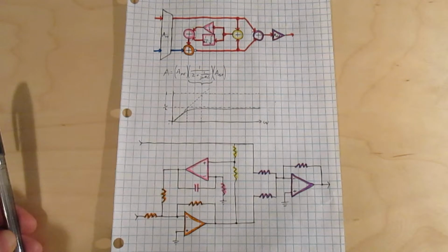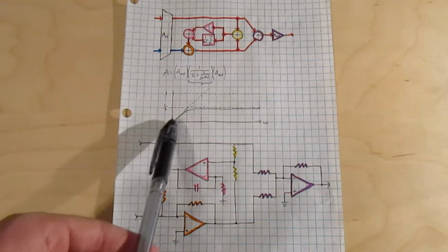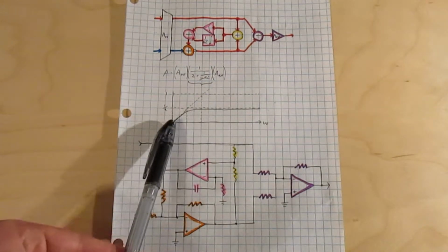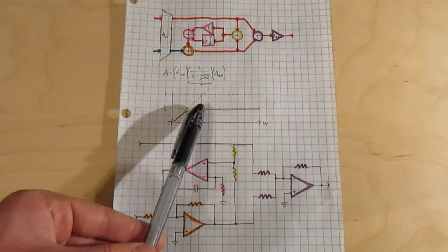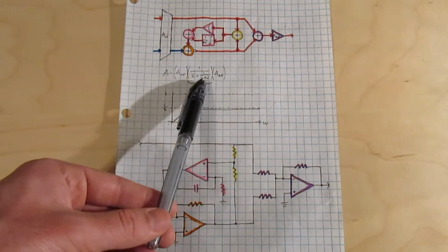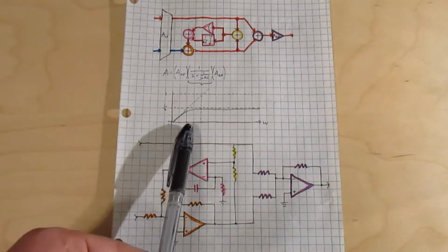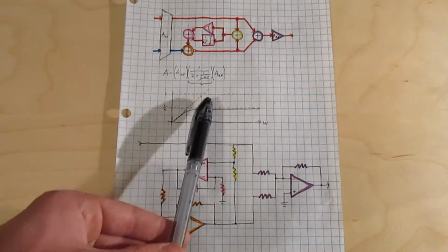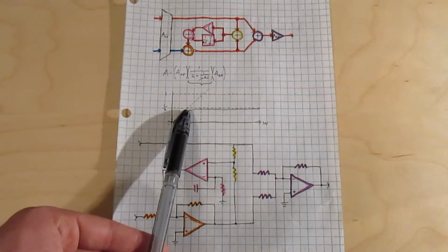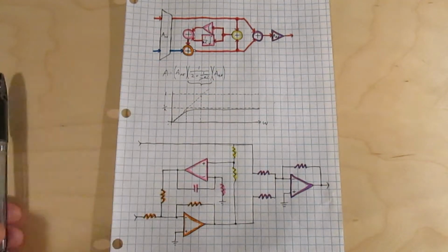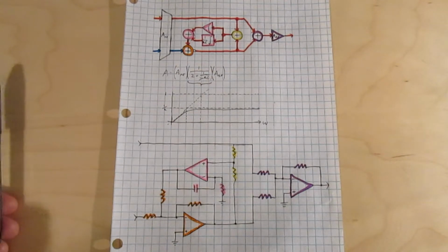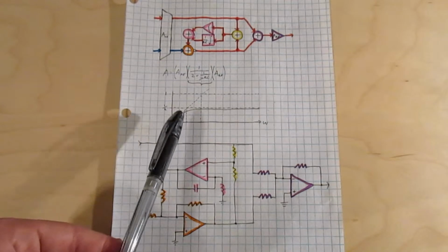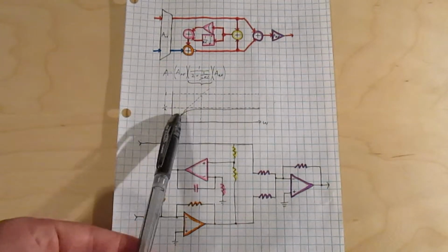But the gain reduction also does something else interesting for us in terms of the frequency response. If you look at the plot, there's some corner frequency where the gain starts to level off, and that's the point where this 1 over j omega RC term becomes less important. So if you look at where it is with a gain of 1/2 and where it would be with a gain of 1, you can see that the corner frequency is actually lower now that we've reduced the gain. And this could be a good thing for us. The heartbeat signal is a pretty low frequency, or at least has some low frequency components, and we don't want that to get filtered out, so it's kind of nice to have a really low corner frequency.